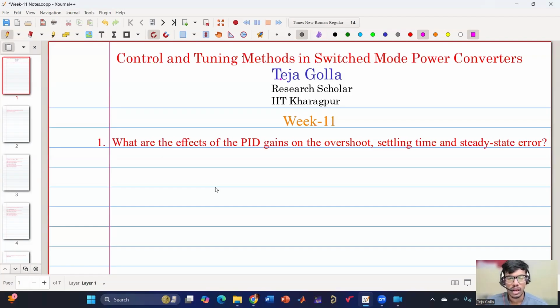Okay. In the last week, I have not taken any session because that was conducted in the last week. Previously we discussed trajectories because we needed them for large signal tuning. We learned how to draw the trajectory, how to get the eigenvalue, stability, etc. And then we discussed the large signal tuning derivations for load transient, how we can design the controller considering the trajectory, and how we can shape the trajectory so that we get near time optimal or time optimal recovery, and what the requirements are.